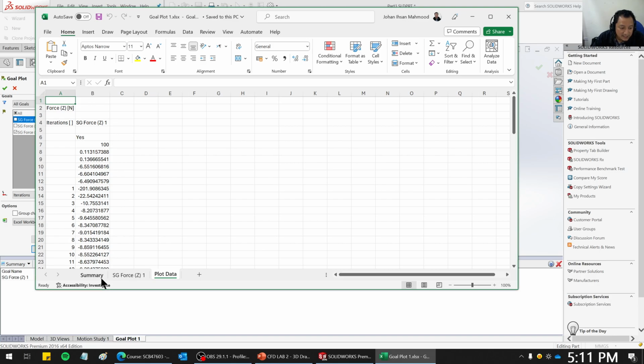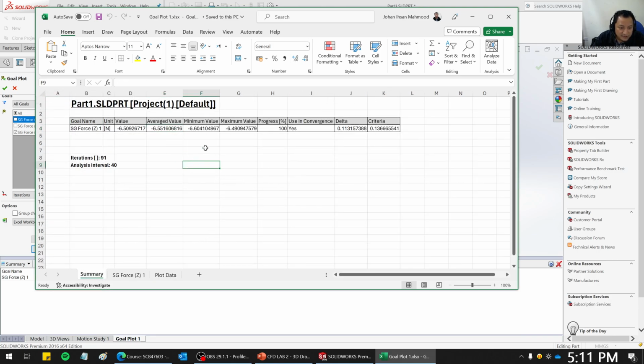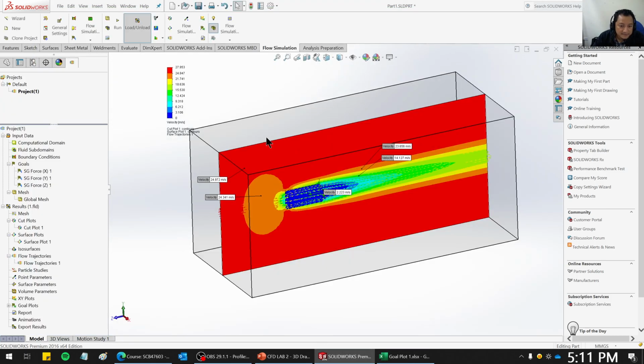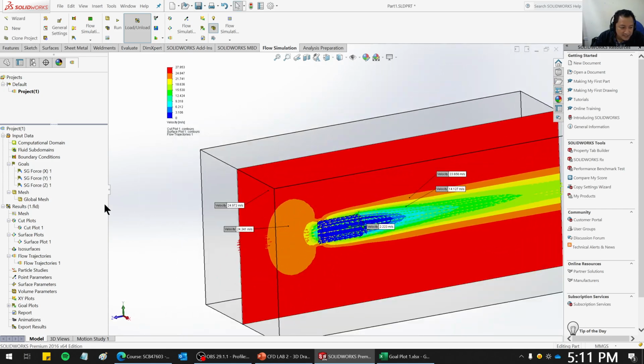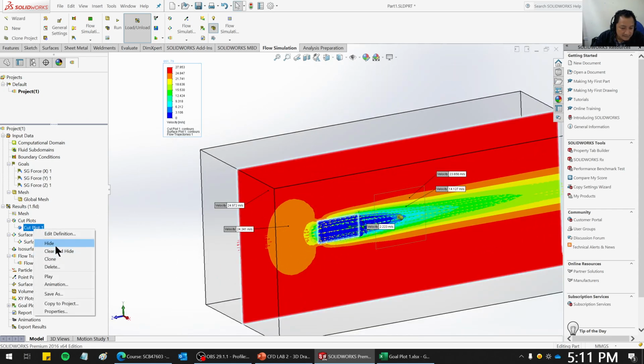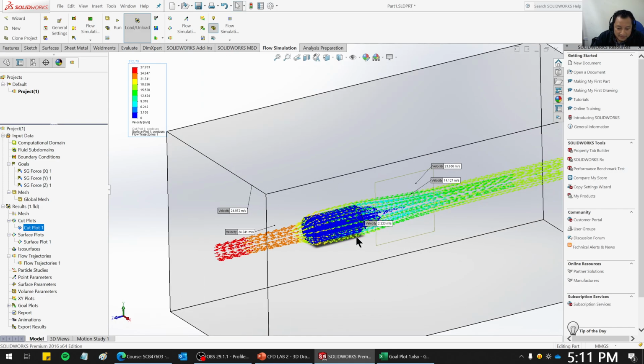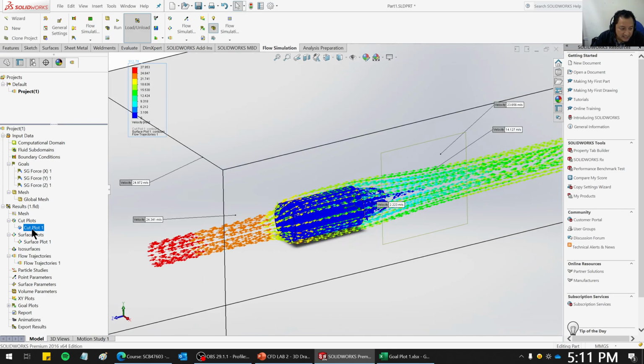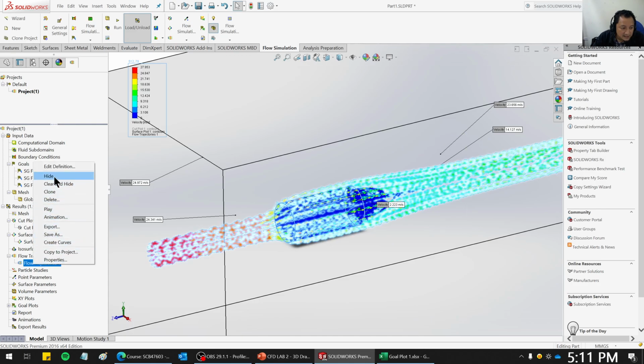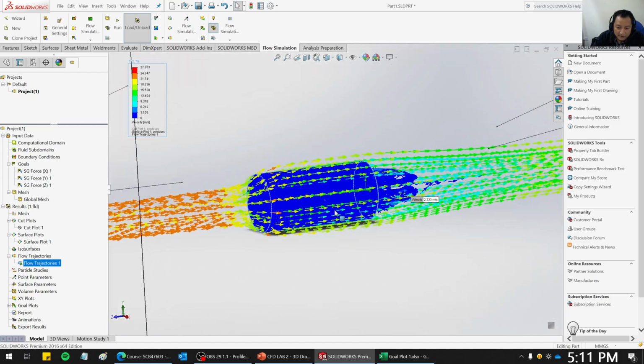and this is the raw data. So the value that you should take is the average. Take 6.55. So this is the drag coefficient of this object, which is a cylinder along the flow, parallel along the flow.